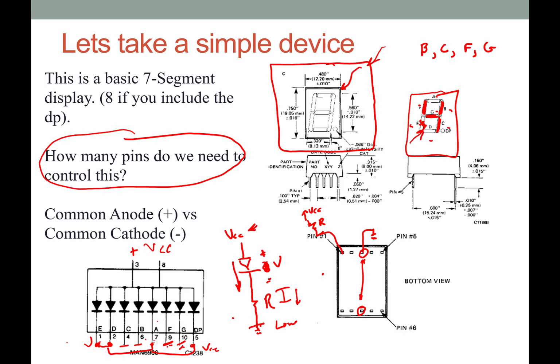When we have a 0 here, for example this, and VCC up there, that's going to turn that particular segment on. I constantly get this confused because I'm talking about them both all the time, but that's the case that we have right here. So when this is a 0 and we tie this to VCC, that will be on, and that's negative active logic. And this is actually the common anode right here that is displayed.